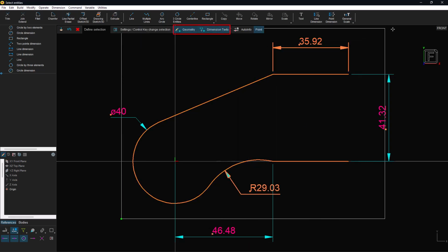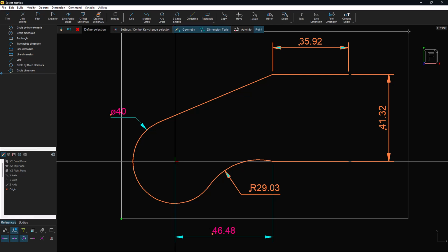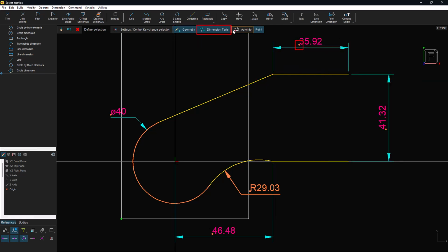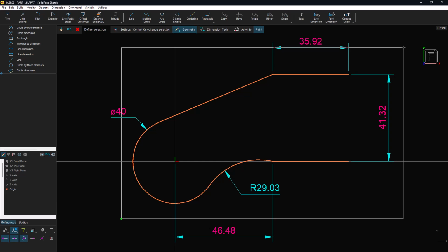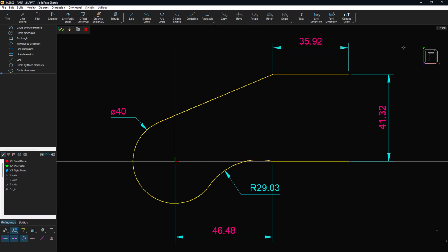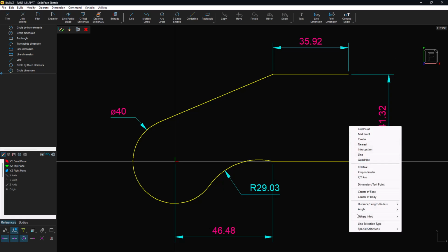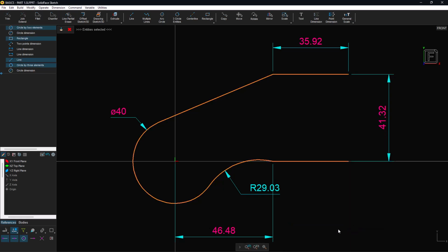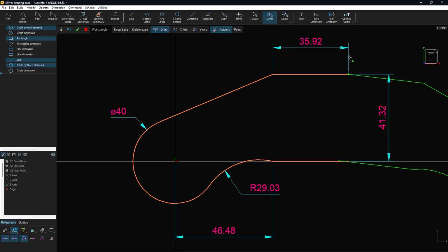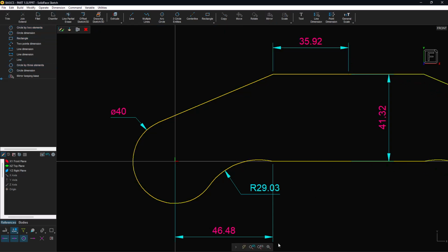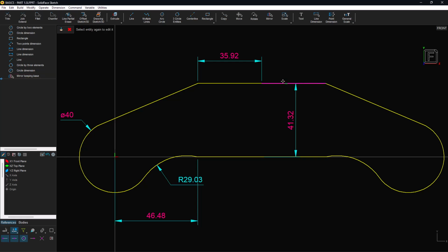Note that you can switch between selecting geometries and/or dimensions. When the dimension is active for selection, a visual mark is shown on each dimension or text. Sometimes you need to select all active sketch geometry. Use the Active Group Selection option for the 2D drawing or sketch selection when the sketch module is active. Activate Mirror. Select the extreme point. Mirror with a 90-degree angle. Join the lines to create a closed external contour.